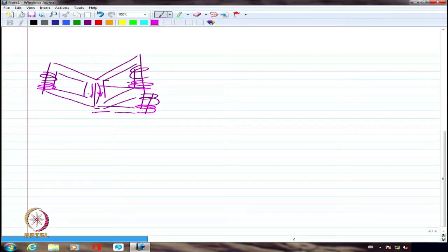So if I have in the middle limb phi A plus phi B plus phi C as the total flux passing through the middle limb, because that is probably acting as the return path for all the fluxes which are coming from A phase, B phase and C phase respectively. This has to be 0 if I am looking at this as a balanced 3-phase current passing through a 3-phase winding. So I'm going to have essentially this flux to be 0.